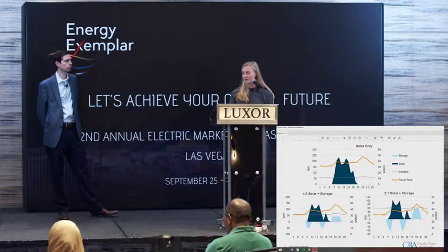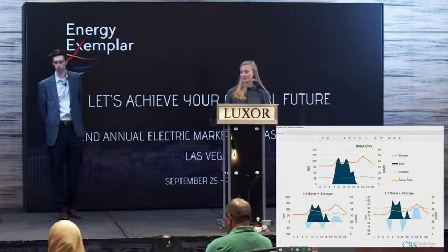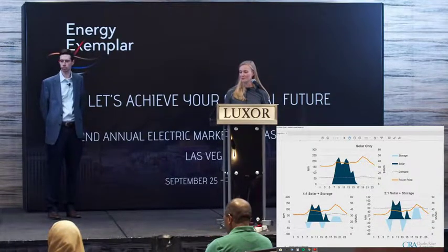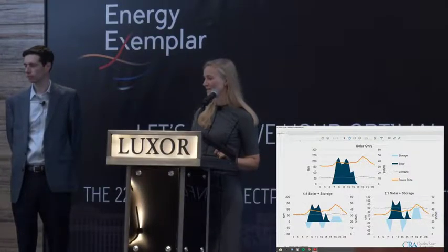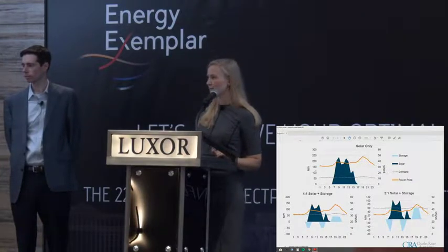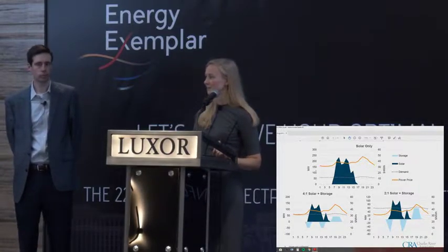And this is a winter day. So that is what you see there. And then in the 2-to-1, it's interesting. You can see this utility is able to almost completely meet its load during those peak hours. So there's a high potential to reduce your exposure to price spikes, specifically later in the day with the storage, especially when you have that higher pairing ratio. But potentially not enough to outweigh the additional cost of the storage.